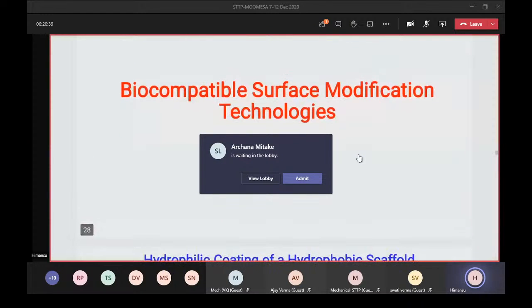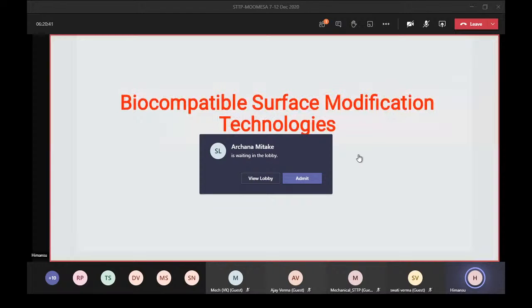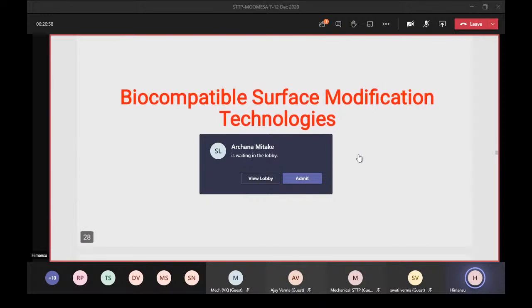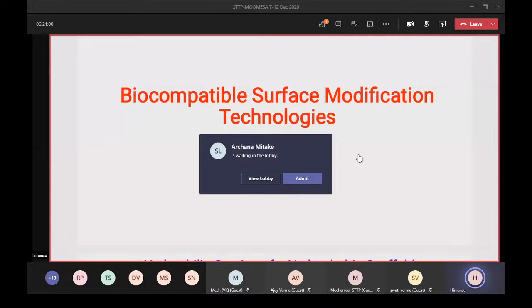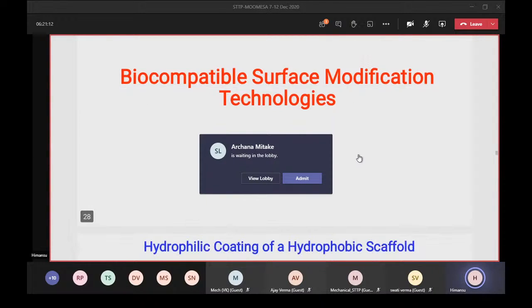This is in order to create a bone tissue engineering platform. As you know, we are all mechanical engineers here, so we know mechanical strength is very important. That means the involvement of hydrophobic polymers like PLA, PLGA, which people commonly use. But PCL, PLLA, any kind of such substrate, doesn't have cell recognition property, so we have to create the cell recognition property over it. How to do that? This can be done by a hybridization process.